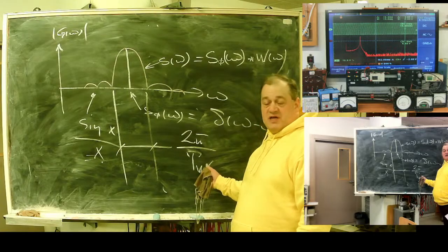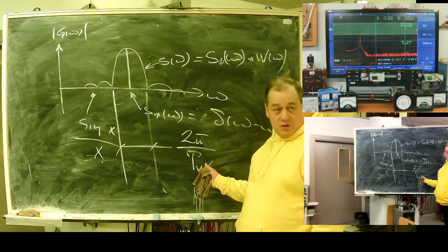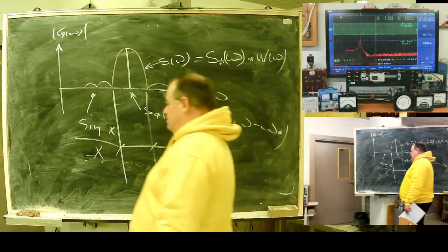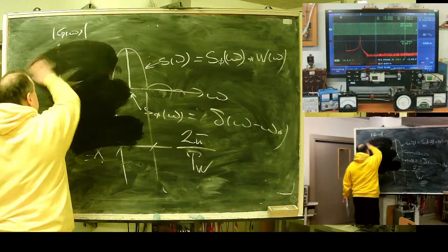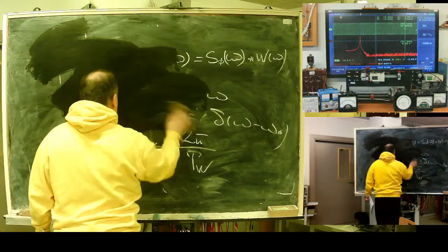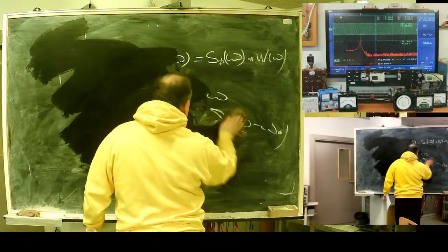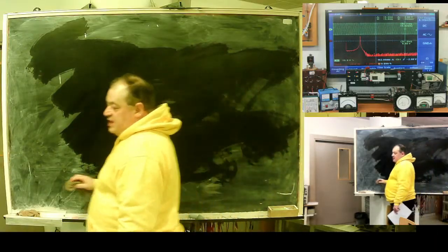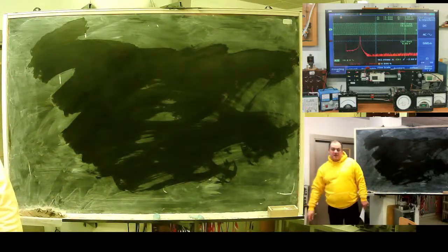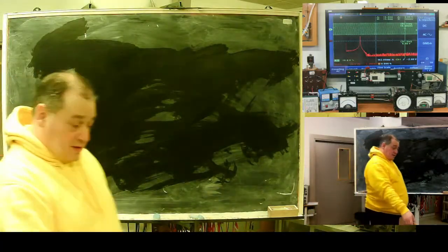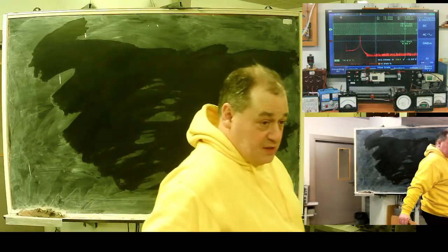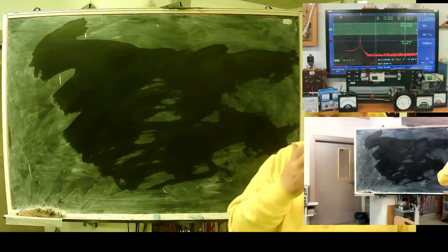Elongation of observation windows means what? Slow down of my device. I need to wait for multiple periods to get a precise measurement. In theory, if for example you do metering where fast reaction to transients isn't required, you need precision.